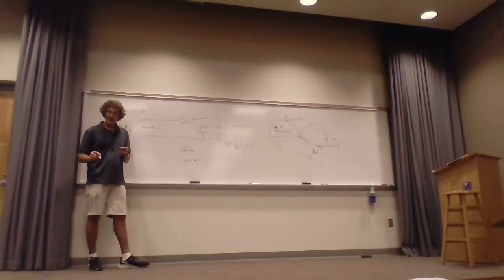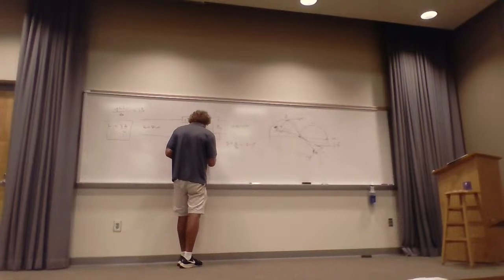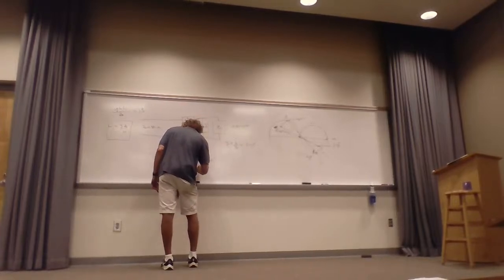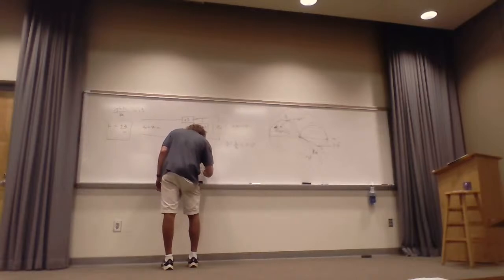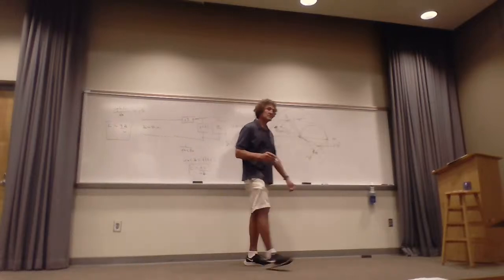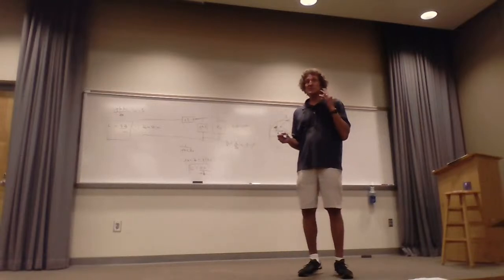Y'all with me? So that's equal to j0.2, or I can say that C is equal to 0.2 over omega times Z naught. And that's how you would calculate the values of L and C to impedance match this.